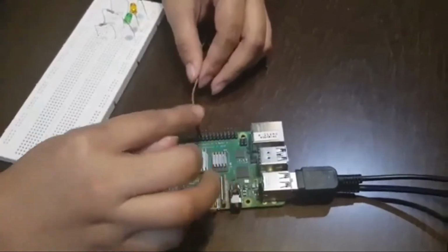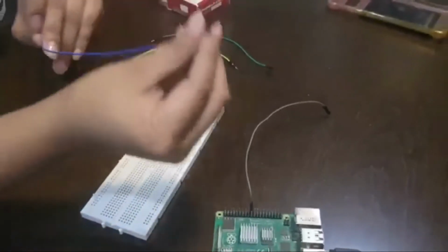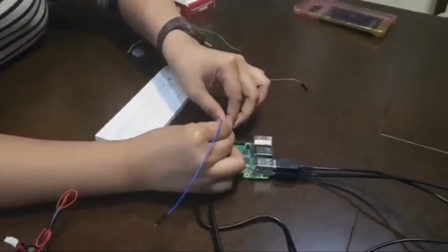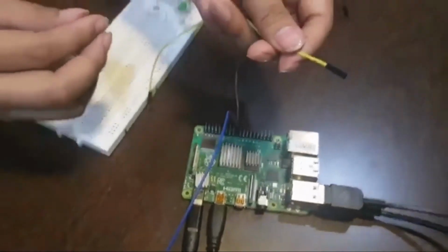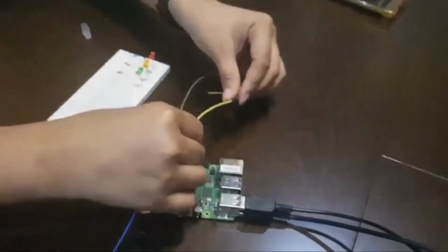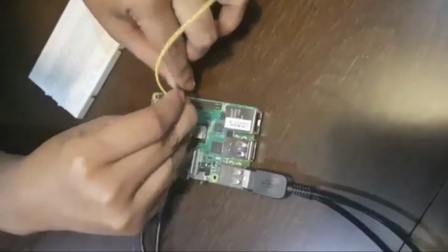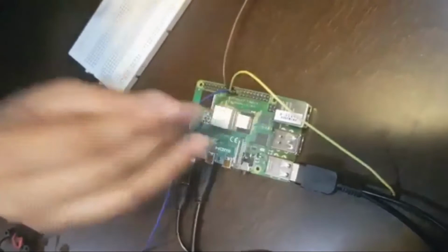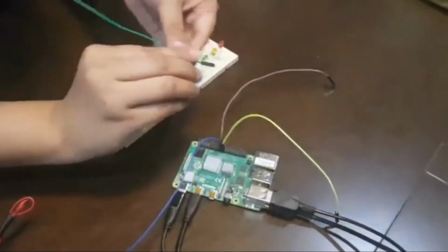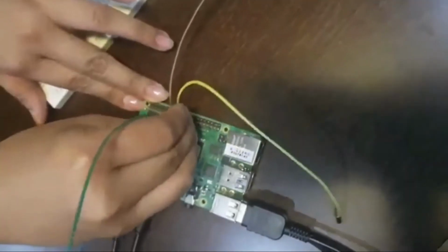We take the female end of the connector instead of the male. The male end cannot connect to the pin. We connected the brown jumper to the 10th hole from the top. This is the ground node. Without the red jumper, we use the blue one and place it on the GPIO 10 directly across the GND jumper. The yellow goes below the blue jumper, which is the GPIO 9. Next to it is the GPIO 11 where the green jumper is placed.